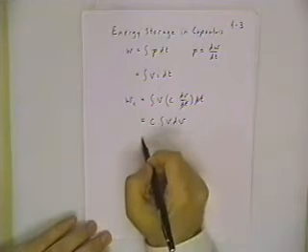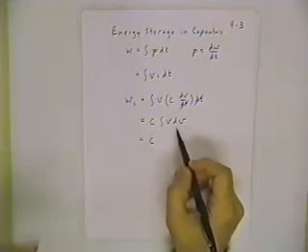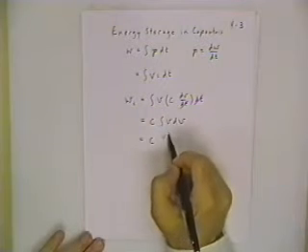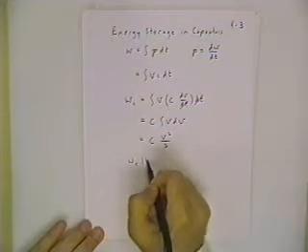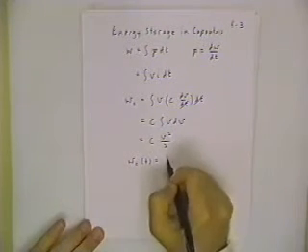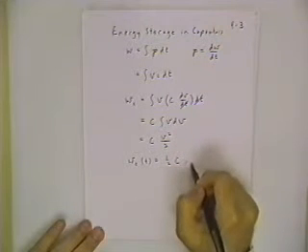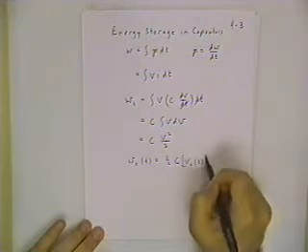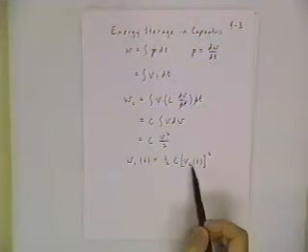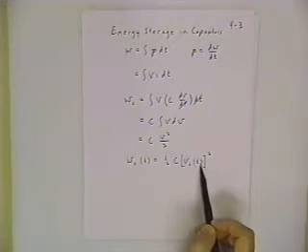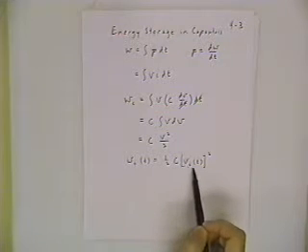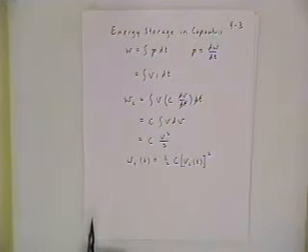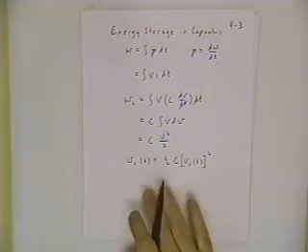And now that's an integral that everybody can do. It's just the integral of x dx is x squared over 2. So here we have, instead of x, it's v squared over 2. So we come up with, as a function of time now, the energy stored in a capacitor is 1/2 CV squared. And I put in all of the dressing here to remind you that it's a capacitor voltage function of time. It says at any instant t, if I know the voltage across a capacitor, I can figure out the energy stored in it. And remember that that energy is stored in the form of electric fields.